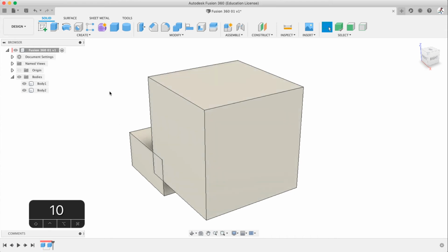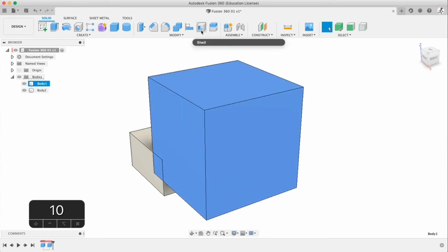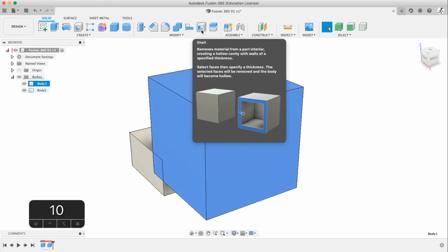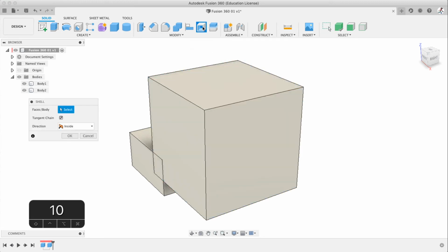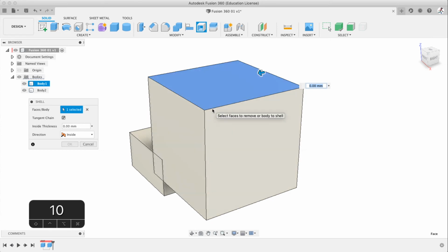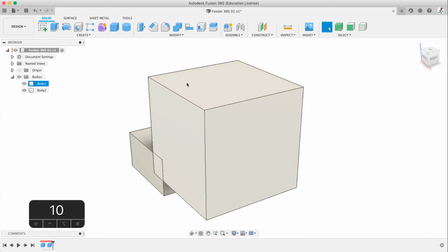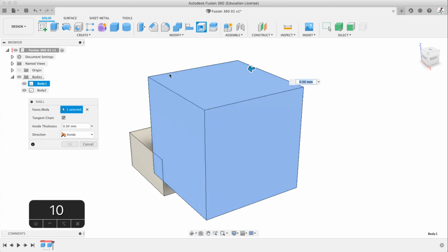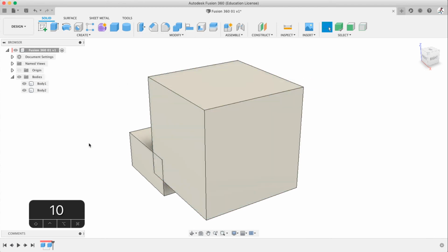Because as one reference, if I select a body and then hit a tool, sometimes on certain tools, it's a different action than selecting the tool and then the body. So if you look here, now it's shelling over this corner, which is a different shell effect than selecting the body and shelling. I'll explain it in future videos, but this is just my workflow. You can do it differently, that's fine, but you might get a bit confused when things don't work properly.